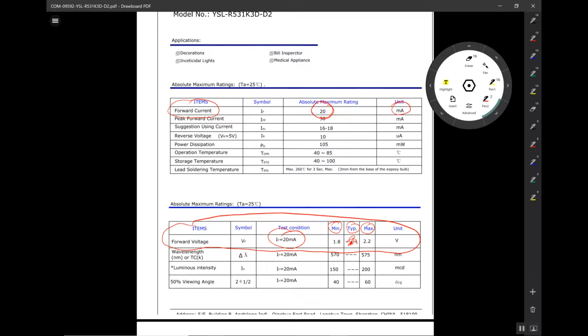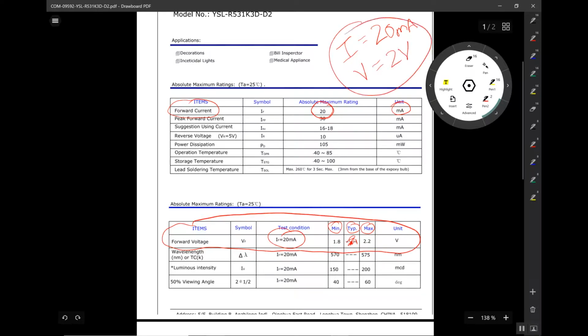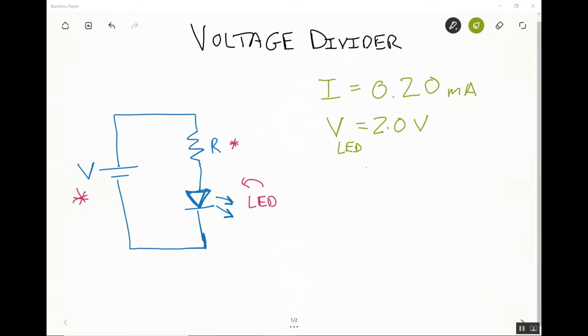It's a resistor that's specifically picked with the correct resistance to limit the current and voltage being supplied to the LED. So we can use this principle of the voltage divider circuit to calculate what that resistance value should be. So we can design a circuit to make an LED work. So let's take a look at a data sheet for a real LED, and then calculate what the resistance needs to be for a circuit where this LED is being powered by 5 volts from an Arduino Uno digital input output pin.